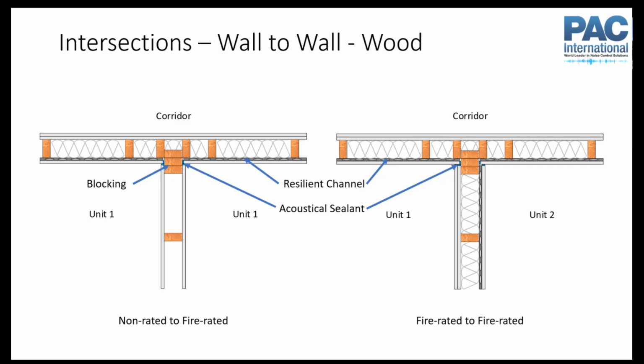So anywhere you've created a discontinuity, a gap, make sure you've got acoustical sealant specified for that. And these can get complicated, and this is why it's always great to bring in an acoustician. I think it's great to have them help select wall assemblies with the right STC ratings, but it's really key to have them dig into all of these details, go through your detail sheets and do this exercise of tracing all these potential transmission paths and trying to optimize these, while of course taking into consideration constructability, cost, fire, and all of these other things.